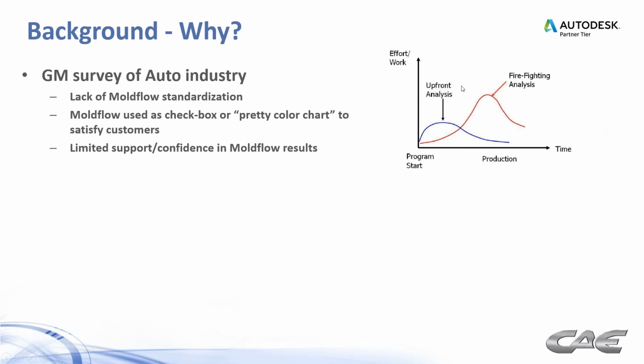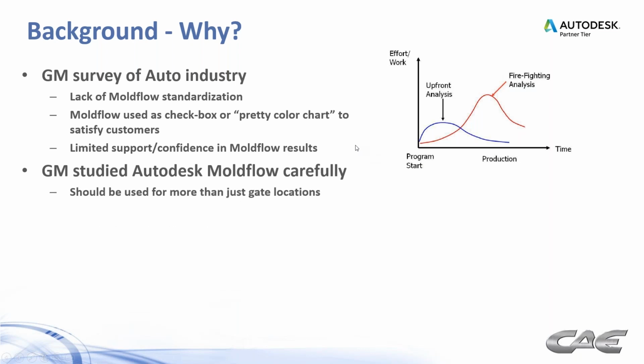And this is kind of a chart that helps explain that. So if you do upfront analysis, the amount of effort and work is less, and things just go better overall, rather than getting into these situations where you're doing firefighting analysis when you're ready to cut steel on a mold. So GM studied Autodesk Moldflow very carefully, and found that it really should be used for more than just gate locations, and that's oftentimes what it was being used for.